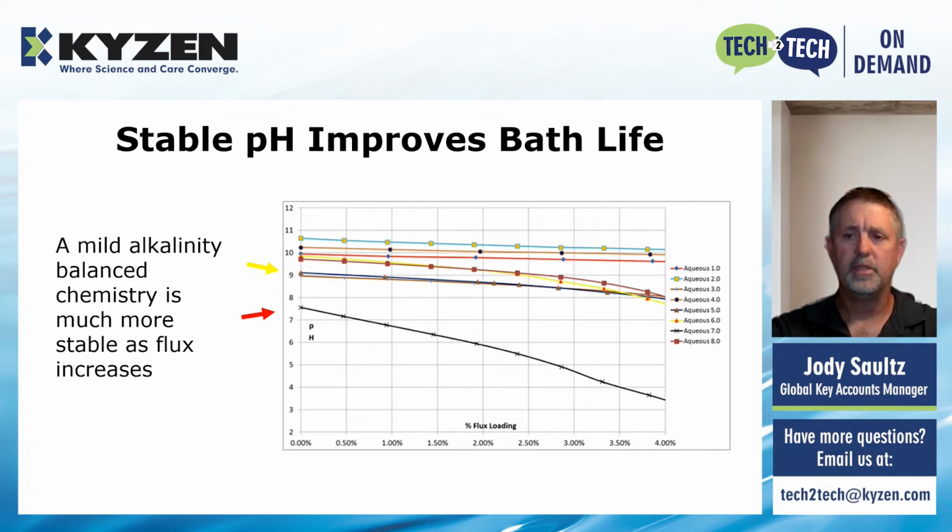Those pH neutral chemistries tend to foam a lot quicker toward the end of the life of their bath, or even through what I would say is halfway through what a good bath should be. And then you could also run into compatibility issues as well as poor rinsing with these pH neutral chemistries.